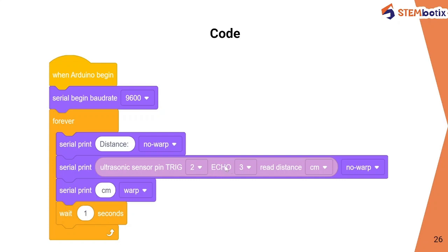Here we just need to add the pins of a trigger pin and an echo pin which are connected to our microcontroller board. We just mention the pins, and the extension automatically calculates the distance, and we don't need to write any manual code, just because we added the extension of the ultrasonic sensor in our Blockzie software.